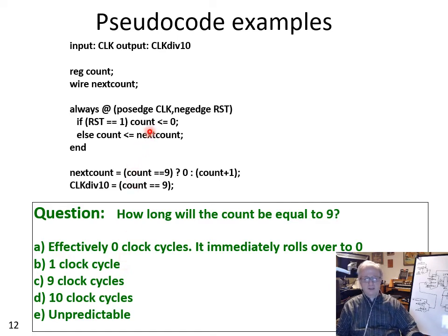I'll also comment on what the diagram for this would look like. I'm not going to draw all of them, but you may wish to do this as a practice for the exam. We have a register, you know how to draw that. We have next state logic. Well, on the previous diagram I said an if then else branch gives you a two-way mux.